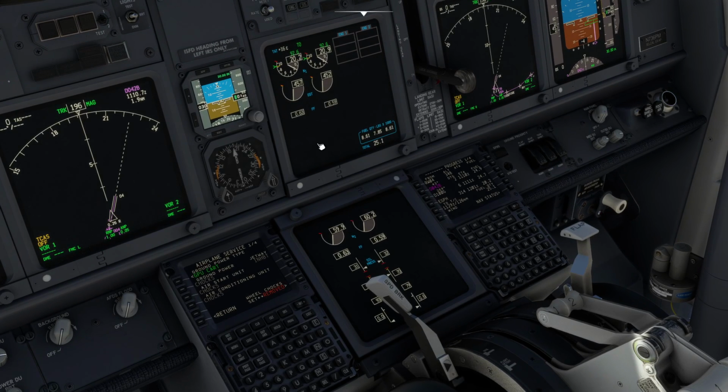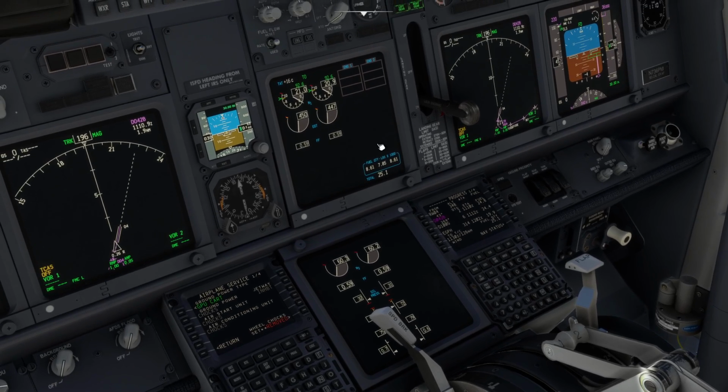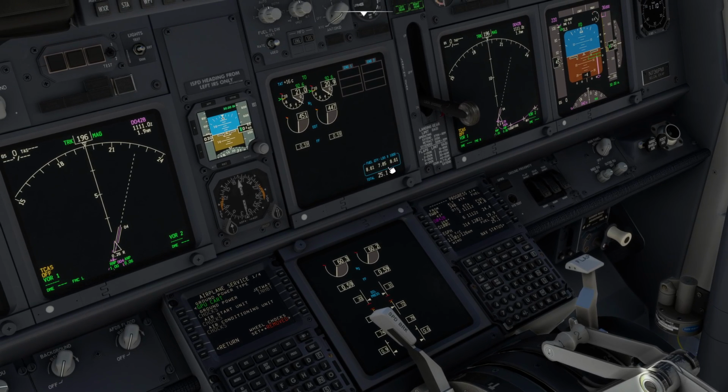You can correct it in flight, and again you'll notice it will drain from the central tank first. So you will get another warning on a longer flight. If you have overfueled your aircraft, the central tank will run out first, and then you'll turn the central pumps off first.